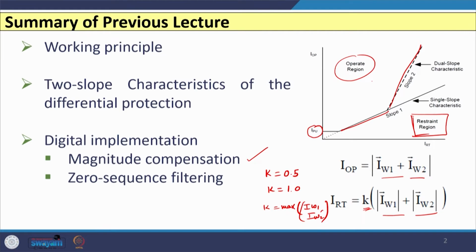And the second point which we have discussed is that in digital relays, the CTs which are connected either on the HV side or LV side are connected in star only. As we have discussed earlier, in bias differential or percentage differential relay, if your HV winding is star connected, then CTs on this side are connected in delta and vice versa.